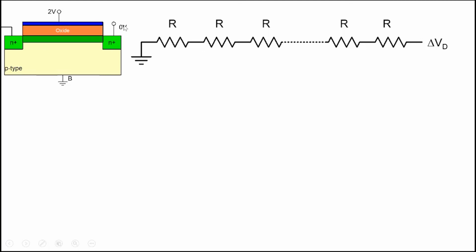When you have very low voltage or 0 voltage applied to the drain here, then the channel is uniform. And when the channel is uniform, you can think of it as being made up of a small set of distributed resistors like this. If you change the drain voltage by a certain amount, delta VD, let's say I increase it by 0.5, it will distribute equally over all of these resistors. A fraction of the applied voltage will appear across this R here, and the current would increase.